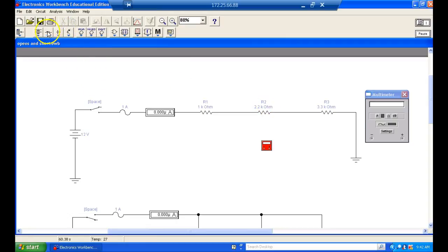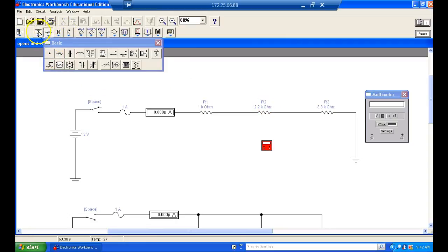in fact, this is the way we would normally make our measurements. Normally we reference one of our leads to our circuit common. A lot of people don't understand that. What we do in electronics is we've got to have at least two conductors, so we use a symbol to represent one conductor. This is a symbol for what we call ground. So we're calling this the common of our circuit, not the common of our meter. Instead of drawing the wire, we represent it with a symbol.